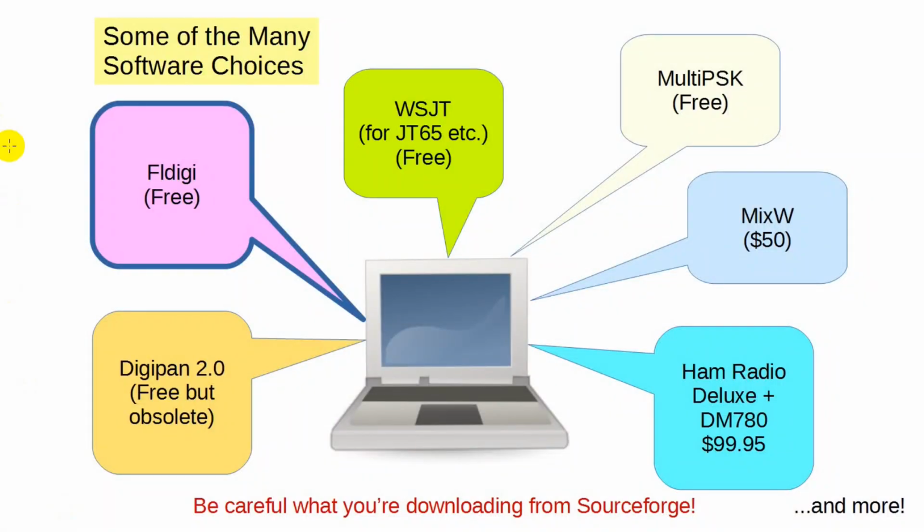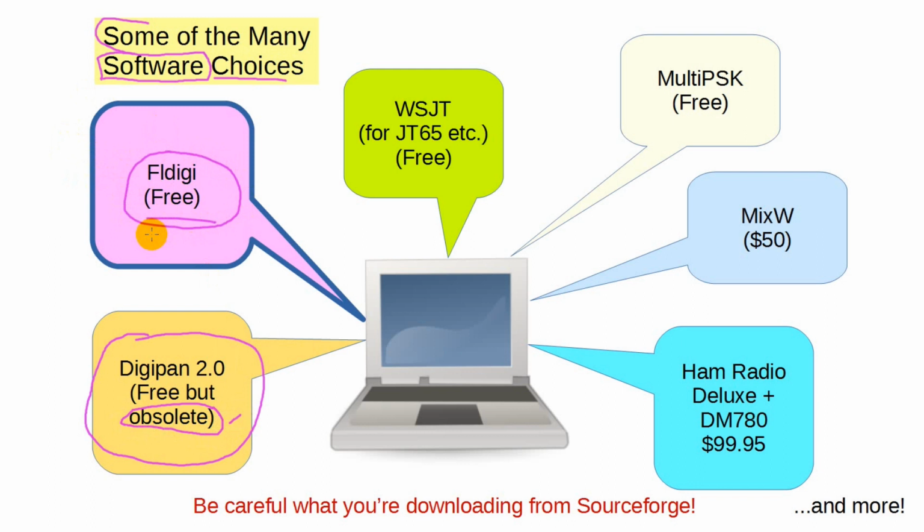Well, okay, something has to instruct the sound card as to what to do. There are many, believe me, many different software programs out there. Good old Digipan is still available, although it was last updated in the year 2000. It assumes using an RS-232 to control push-to-talk, so its relevance has diminished to near zero. For general purpose use, FL-Digi is very popular, very capable, and is free. Lots of people use it.